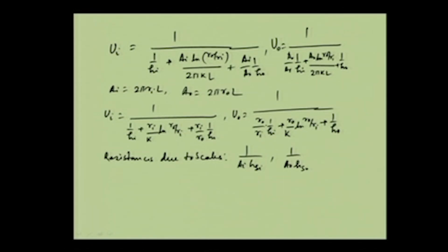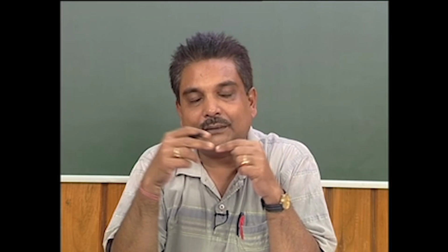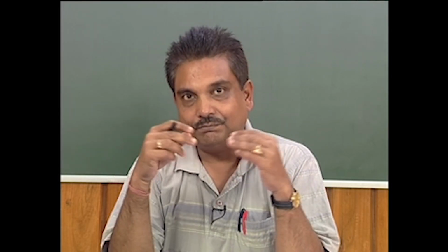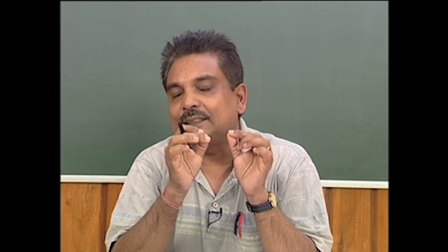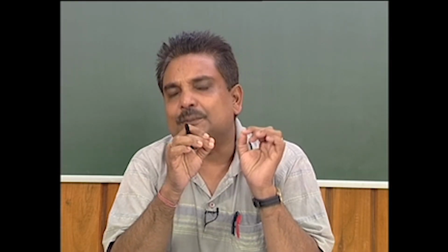What are these? HSI is the heat transfer coefficient for the scale at the inside surface of the inner pipe. It is expressed in terms of an equivalent heat transfer coefficient, because though the scale is a solid material and the resistance could be written in terms of thickness, it is difficult to measure the thickness of the scales that are formed, as it is a very fine amount.